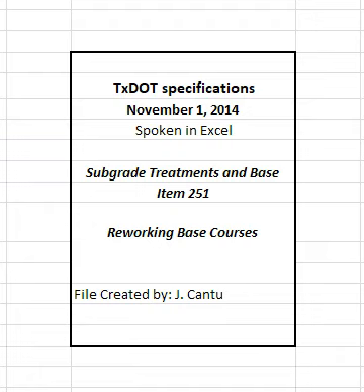Where subgrade is constructed under this contract, correction of soft spots in the subgrade or existing base will be at the contractor's expense. Where subgrade is not constructed under this contract, correction of soft spots in the subgrade or existing base will be in accordance with pertinent items or Article 4.4, Changes in the Work. Removal of existing asphalt concrete pavement will be paid for in accordance with pertinent items or Article 4.4, Changes in the Work. Additional restrictions for measurement and payment are as follows.